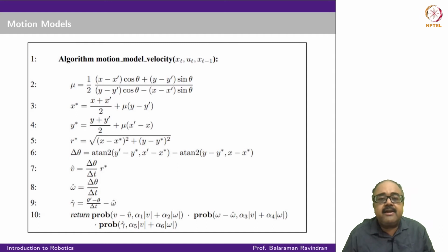It's an independent value that we know, that's given to you as part of xt. So to account for the noise in the angular rotation, we take the actual angular distance that's traversed, find out what the actual angular velocity should be, subtract the number that we already computed, which is omega hat, and call this correction to the angular velocity gamma hat.